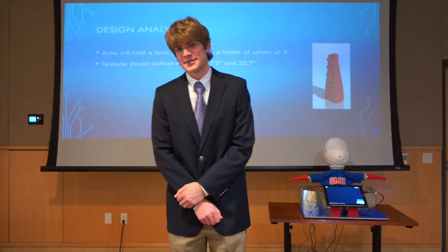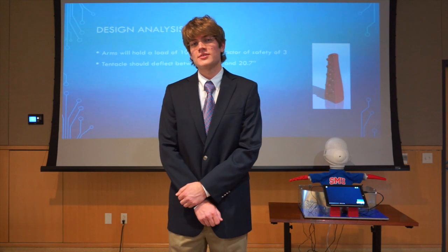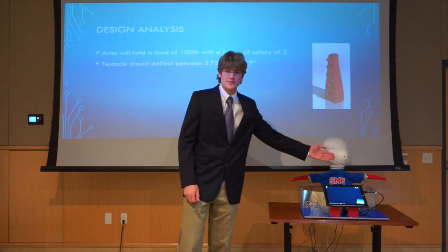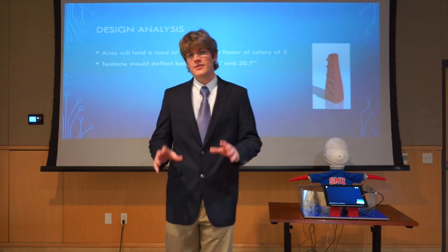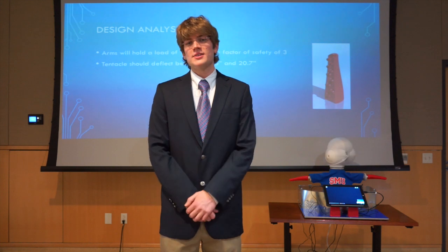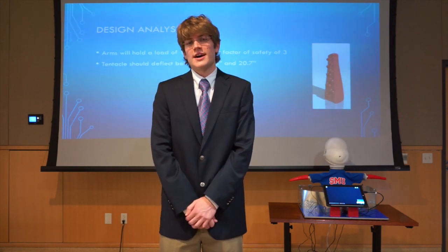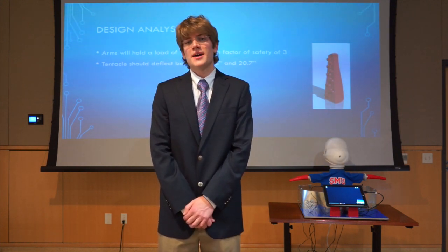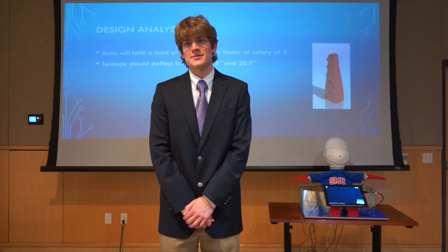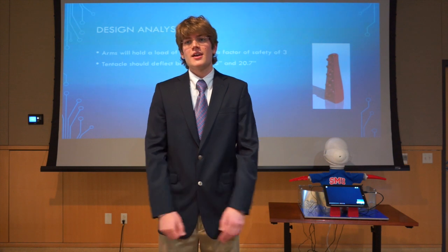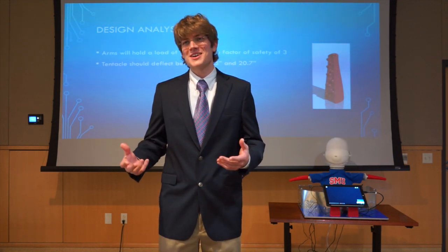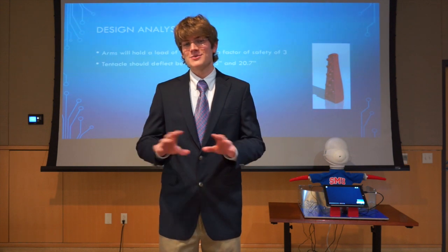In the design analysis, we began by analyzing the strength of the arm. The arm is a 2-inch PVC pipe that crosses over, and we were trying to figure out, will that PVC pipe handle a significant load? And so we did a SolidWorks static analysis of applying 100 pounds of force on the sides of the arms, say if someone is trying to push themselves up. And then we found that there was a factor of safety of about 3, so we didn't need to worry about that.